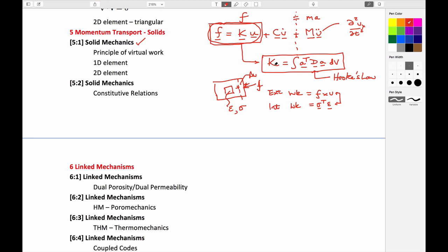We've called all of these matrices K because they've been referred to as stiffness matrices for a one-dimensional element, for a triangular element, and then we've talked about different forms of the constitutive equations. The different forms of the constitutive equations are merely the fact that when we talked about flow problems, if it's flow just within a plane, we could ignore the flow in the orthogonal direction just by putting the conductivity for that equal to 0, basically, because there's no gradient in that direction.